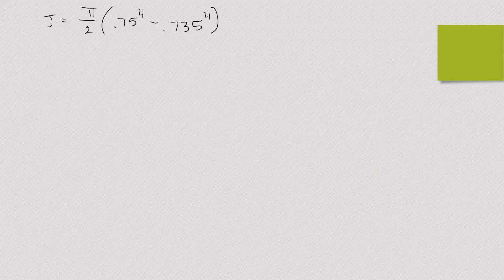Okay, so you're saying that the shear stress equals TR over J? What's that? J times G, right? That's not this equation. There is an equation with JG. What equation is that? Yes, the angle of rotation.